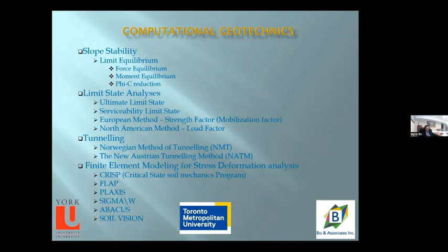So people may not allow your design to be defined until the ultimate conditions. So there will be some limit state required because your neighbor may not want his house footing to settle more than 1 millimeter. They can specify it. So limit state analysis developed ultimate limit state and serviceability limit state.